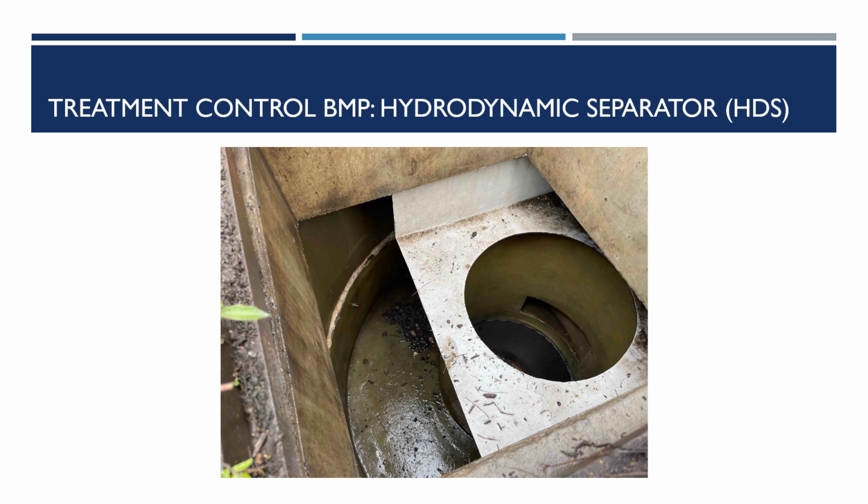Facilities that include parking, fueling, maintenance, and washing for vehicles should consider units that have oil storage. The pollutant removal performance may vary depending on the type and model of the proprietary HDS unit selected for the project. Therefore, project proponents need to review the manufacturer's specifications to determine if the HDS unit will sufficiently remove targeted pollutants.